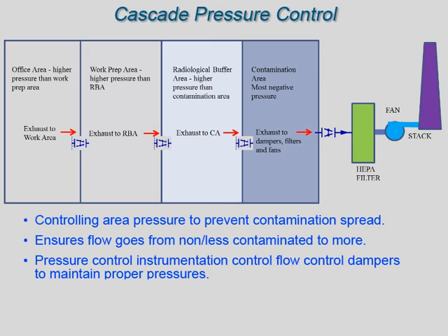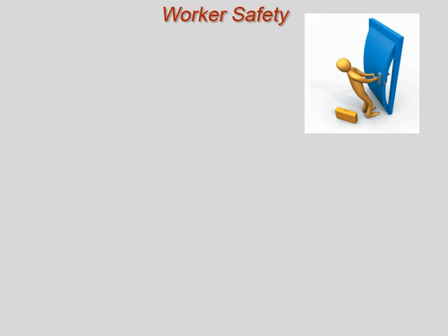By the use of flow control dampers and flow instrumentation, the ventilation flow can be manipulated to maintain areas at higher or lower pressure than others. By using opposed blade dampers to control flow and backdraft dampers to prevent reverse flow, area ventilation reduces the chance that contamination will spread. Small pressures on large areas can cause considerable force.